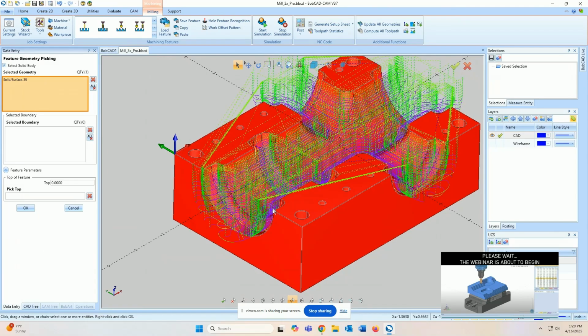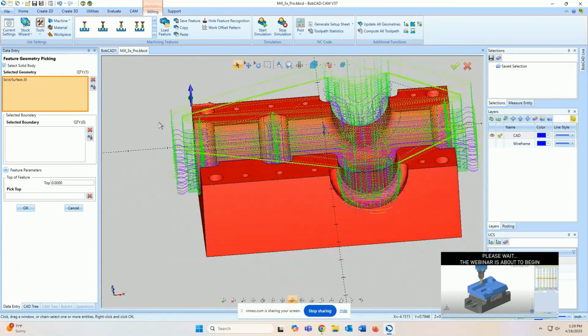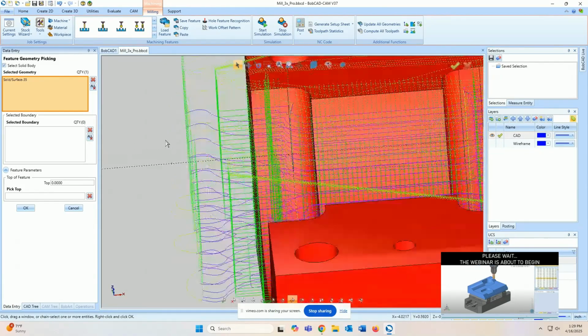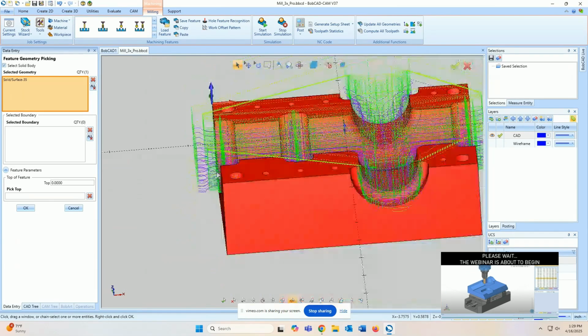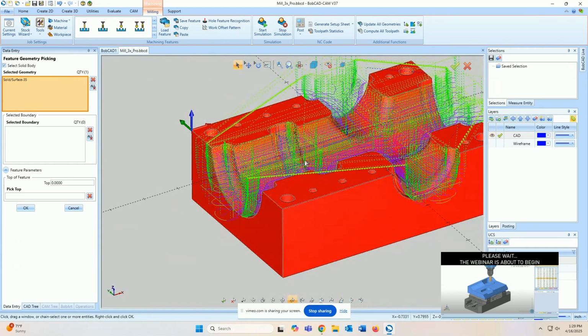so we don't have to create a boundary. And a big reason why I don't have a boundary on this one is because we can go past this surface edge, and you can see the toolpath out here. It's going to start down here off of the stock and work its way in with the side of the tool. So that's going to save us life of the tool, I would say, rather than plunging down in with the tool. We're using the end mill, the end of it, so we're starting from the side of the stock, working our way in.